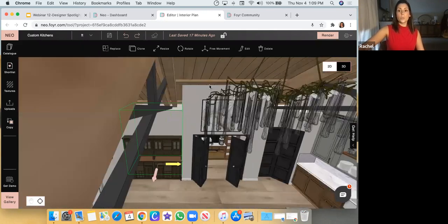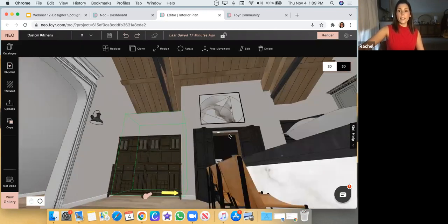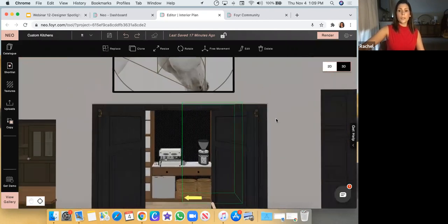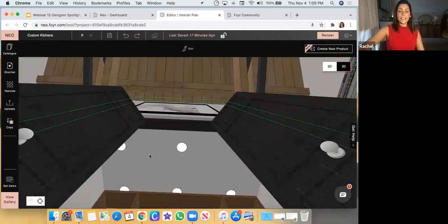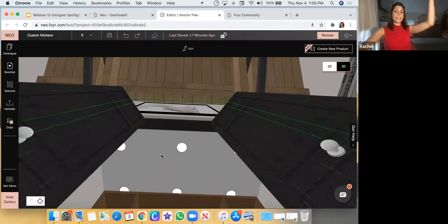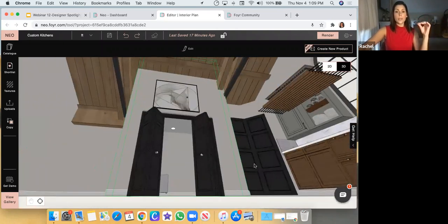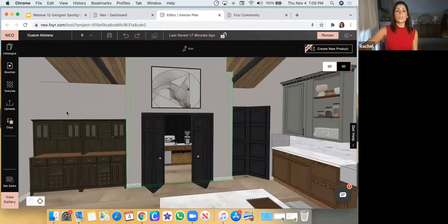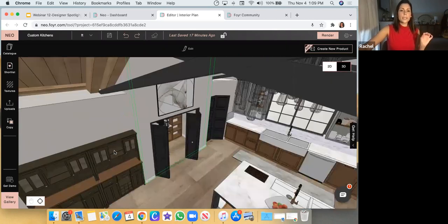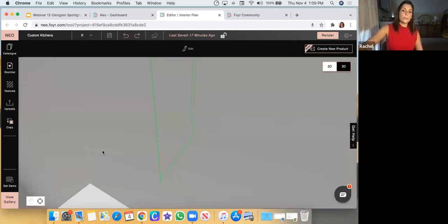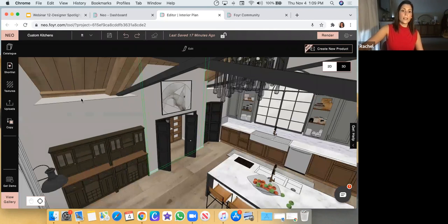Okay, this was drawn with literal walls, and then this ceiling here was made with a ceiling docked cube again that I brought down this time and then applied the recessed lighting to it directly. So there's lots of different ways to create different heights, or to also just, if you have a lower unit here, to kind of cap it off. Let me know if this is making sense or not. Because I had just a straight rectangle across and didn't need anything custom, I was able to use, in this case, just a cube and resize it straight across.